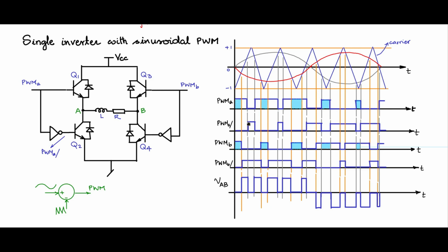The switching on and off doesn't happen instantaneously. There is a finite time. So in a finite time, you will see that Q1 is going from the on state to the off state, and in a finite time, Q2 will be going from the off state to the on state, and in between they will be in the active region for some period of time when both will be conducting.